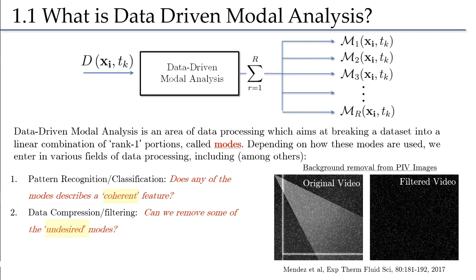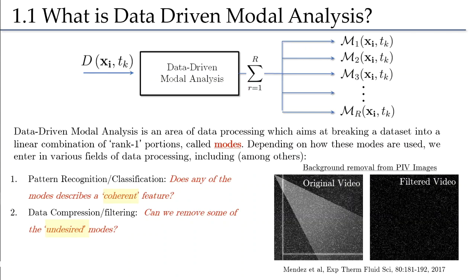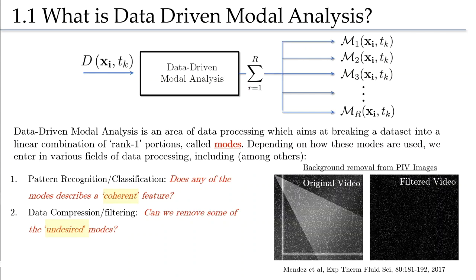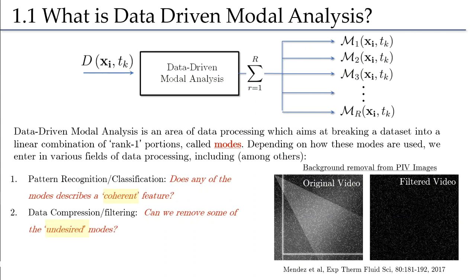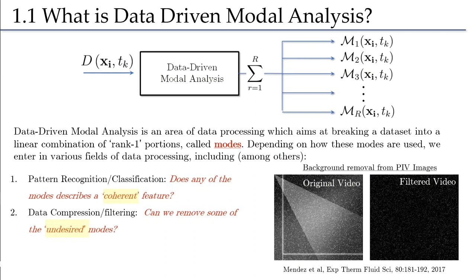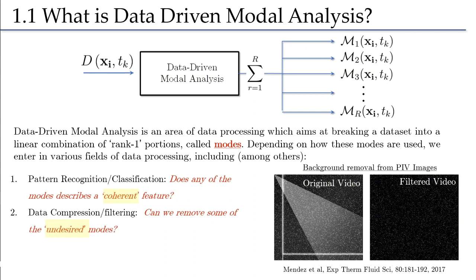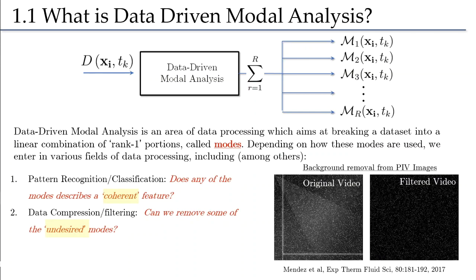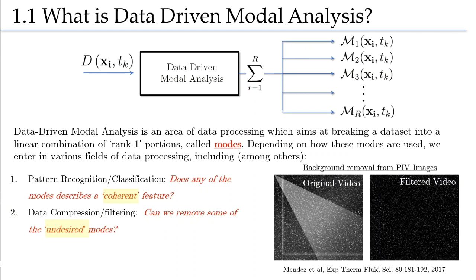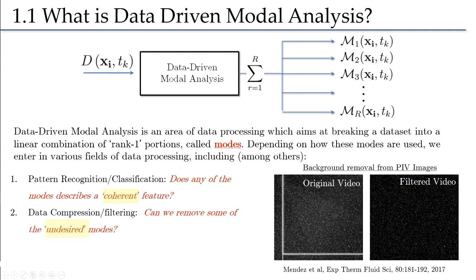This algorithm is based on modal analysis of the grayscale videos. We can show in fact that there will usually be some modes linked to background reflections and noise, and other modes linked to PIV particles. So by projecting the first and keeping the second, you can obtain beautiful and noise-free PIV images.